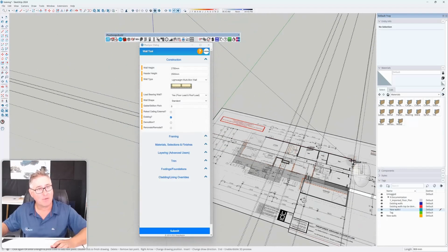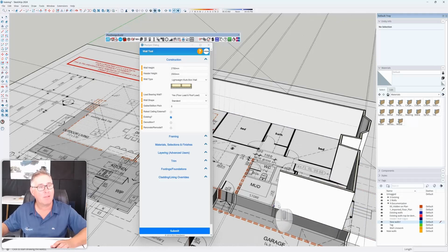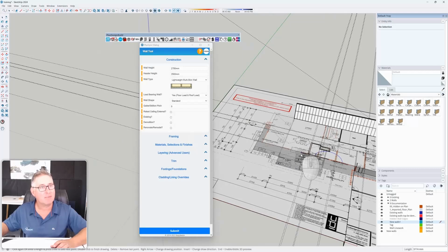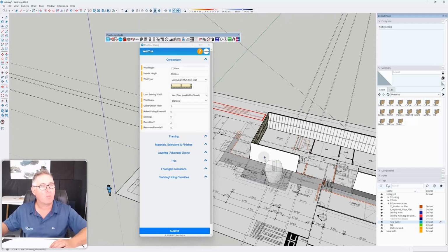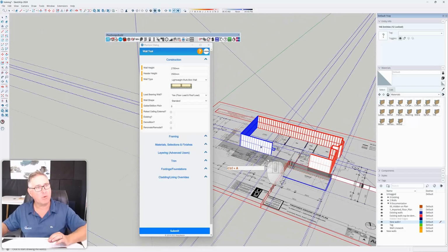Right, so I'll quickly go and draw the existing walls here. I won't get too caught up. Roughly here. As you can see what's going on, I'm not really spending a great deal of time. Right, these are all my existing walls, and then my new walls, I turn that off and draw them over here. Say here, new wall, new wall. Right, when I go Control A, you'll notice that my new walls are blue and my existing walls are red.